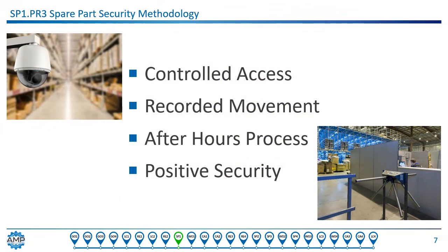The third process in spare parts storage is spare part security. Security is not really about not trusting people as much as it is about preserving the storeroom processes and storeroom accuracy. On the other hand, there's generally a lot of money tied up in a storeroom, and some parts are useful and valuable outside the use intended for the business. So, security. Small steps are usually necessary to implement this practice, going from free access to parts and lax record keeping to access cards and computer checkout systems is usually a traumatic experience for the organization. Going from chaos to a little less chaos and everybody staying happy is a sustainable victory.